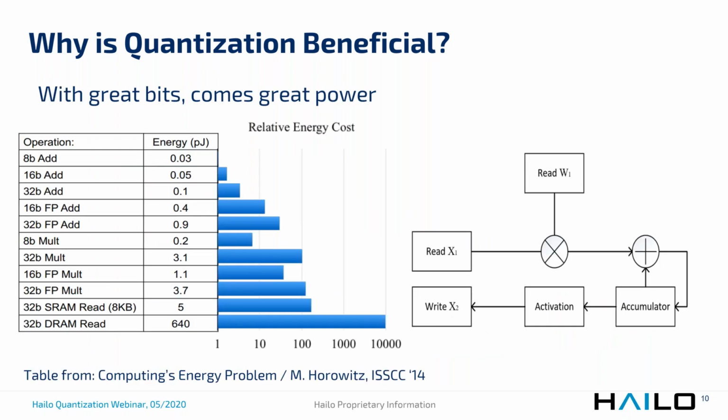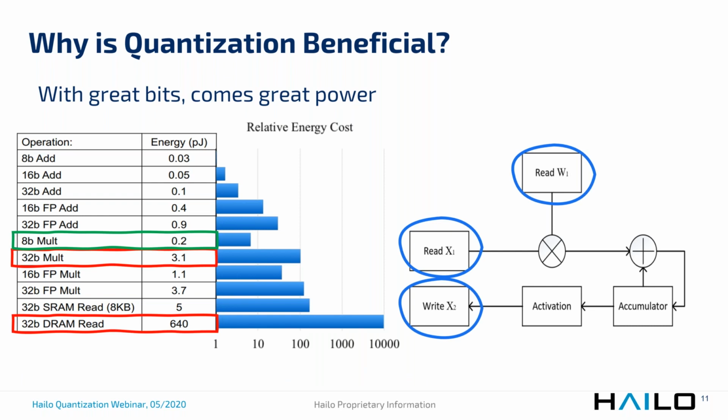So it would seem then that most of the power would also be drawn by these units. However, that's not the case. In fact, most of the power consumption is happening when we access the memory, whether it's for reading or for writing. The operation of accessing an external memory is 2 to 3 orders of magnitude larger than the operation of multiplying two numbers.